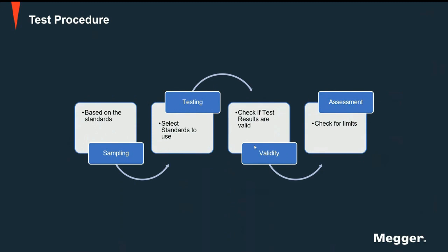When I say validity, we look into the repeatability of the test. Sometimes you will experience that you got this voltage, and then, for example, let me use the pen here, the first breakdown is 10 kV, and then the second breakdown you got, for example, 50 kV. This is not acceptable. Why is there a sudden increase of the electric breakdown voltage?